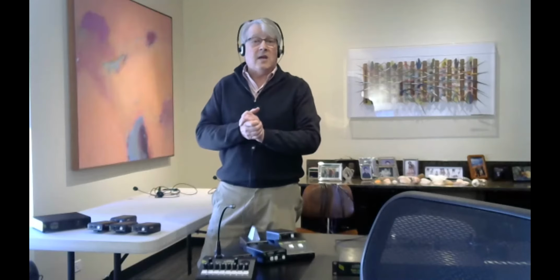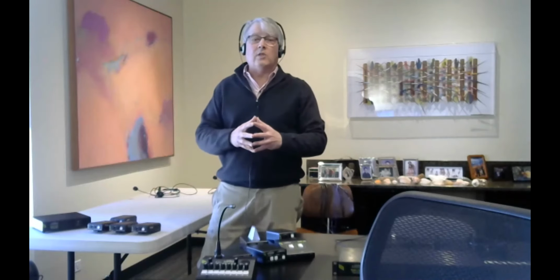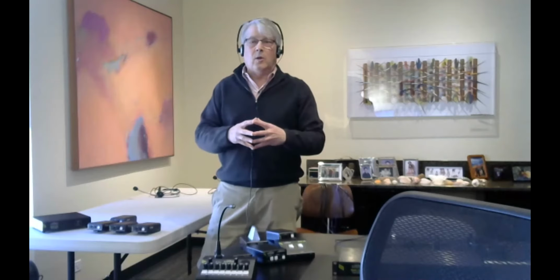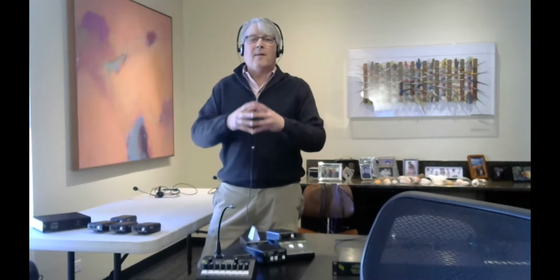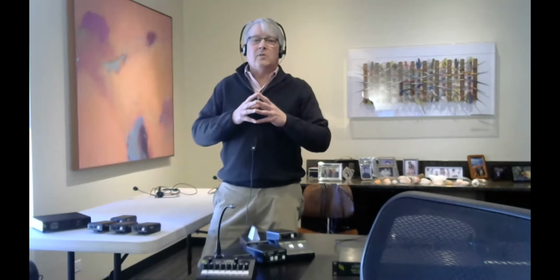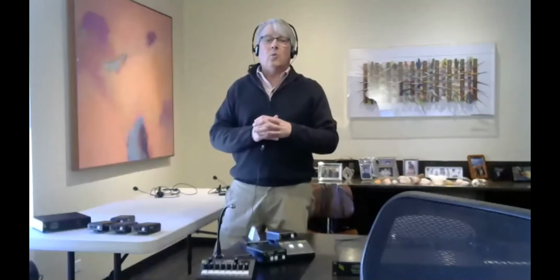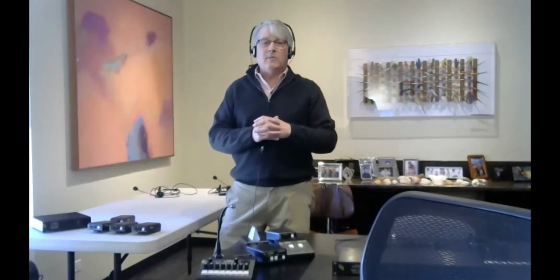Okay, so we've talked about the fact that these are really 4-wire devices, but we electronically make a Partyline, and to the user, it sounds great. It sounds like when I talk, everybody hears me. When any of those people talk, I hear it. But really, what we're creating in this intercom engine is a set of what we call mix minuses. That's, again, an old broadcast term, which is everything in the mix but me, because you don't want echo, you don't want level buildup. So basically, if you have 4 belt packs, each user wants to hear everybody else, but not themselves directly. And I'll talk about how you hear themselves. So user 1 wants to hear user 2 through 4 at full level. User 2 wants to hear user 1, 3, and 4.